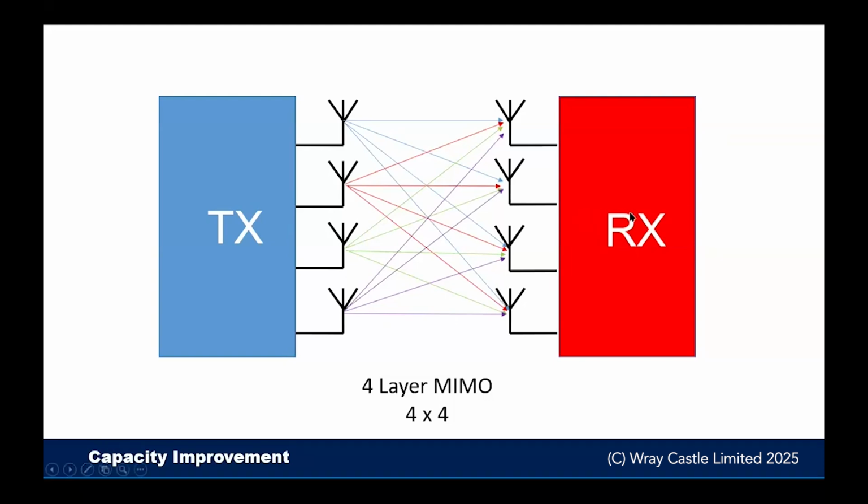The problem with the receiver is not going to be the problem that we have in a commercial mobile network. Your mobile phone, my mobile phone is a small handheld device. Putting 4 antennas spaced apart as widely as possible is difficult in a mobile device. And having 4 receivers and the processing power to handle all the information is going to be quite battery unfriendly. But of course, when you're talking about kit located on a train, the so-called cab radio, space isn't really that much of a limitation compared to a handheld mobile device. So MIMO configurations are a way of maybe compensating for that lack of capacity if we're going to be using a 3 megahertz radio channel.